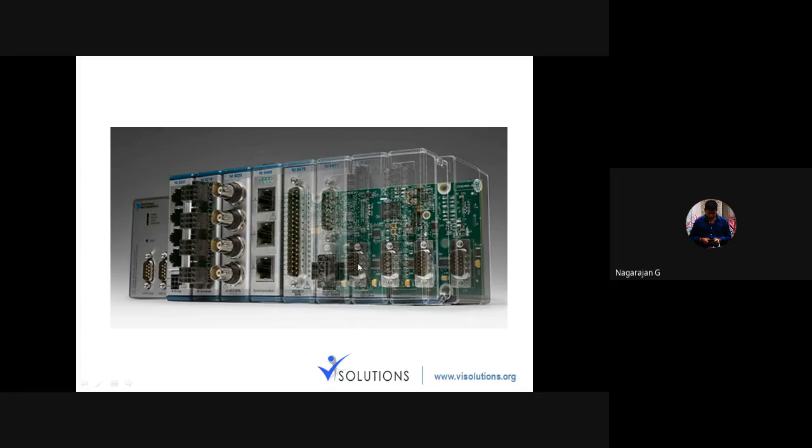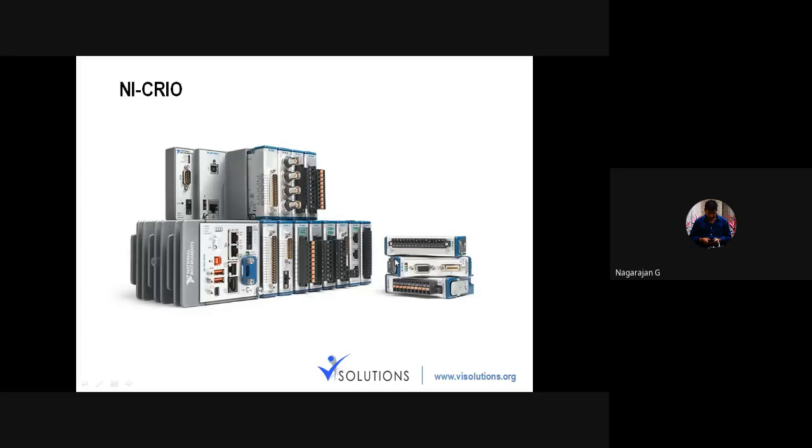All these pinouts are directly connected to the backplane of your chassis. The backplane will have your FPGA. So all the inputs and outputs will be directly connected through the FPGA. And this is a type of hardware we call CompactRIO, where your chassis and your FPGA are integrated.